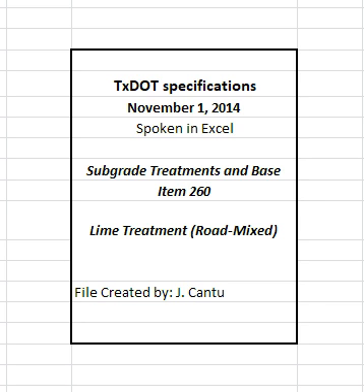Do not allow equipment on the finished course during curing except as required for sprinkling, unless otherwise approved. Apply seals or additional courses within 14 calendar days of final compaction. Table 2. Minimum curing requirements before placing subsequent courses. Untreated material and curing in days. Untreated material PI less than or equal to 35, with a curing of 2 days.